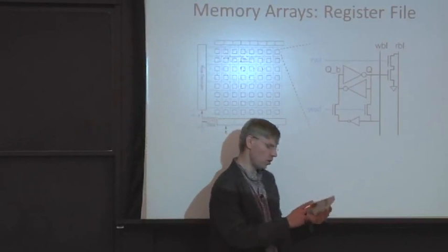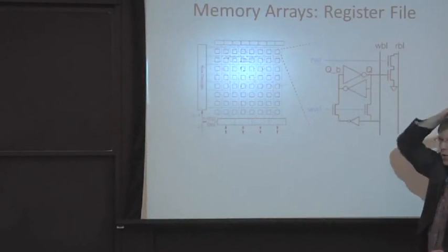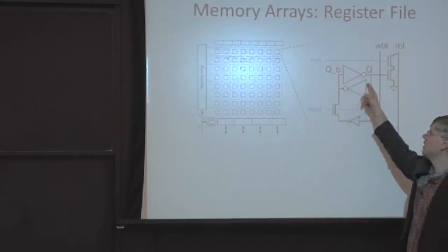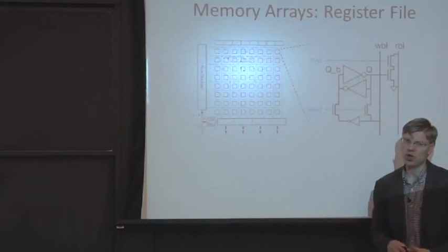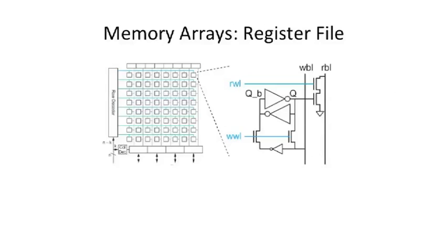And in this register file, I wanted to just walk through what the circuit level diagram over here is. Here we have 2 cross-coupled inverters. And as you'll see, we don't have full complementary logic connecting these two things. But this is a stable storage cell. If you give this power, it'll store data. If we want to do a read, we need to connect the output of this to read bit lines.